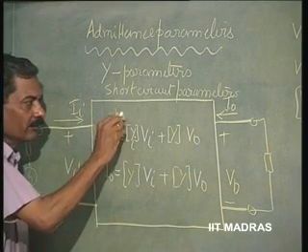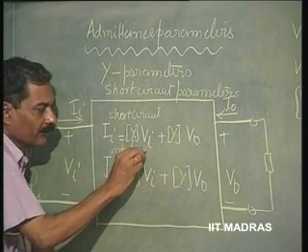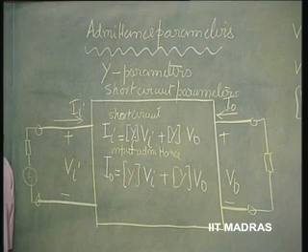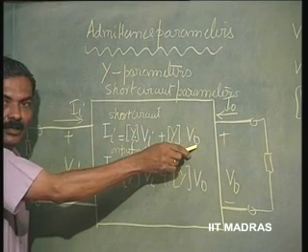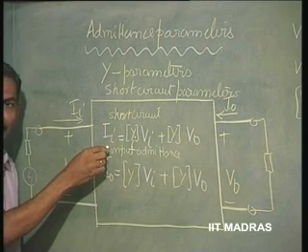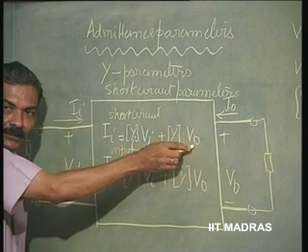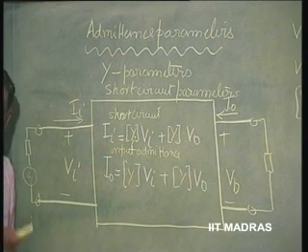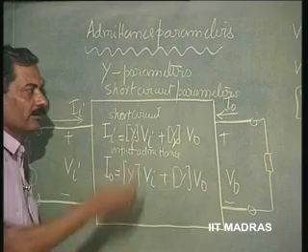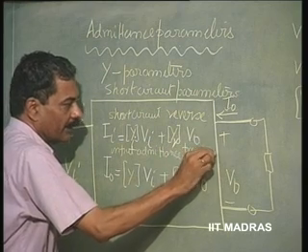That is called short circuit admittance, input admittance. So, short circuit input admittance. This is Yi. Now, II is related to V0. That is, when there is something applied at output, that gets translated to input as II. When Vi is 0, that means input is shorted and the current flowing in the input because of the output voltage is called reverse transfer admittance. Okay, so this is YR it is called. This is the reverse transfer admittance.